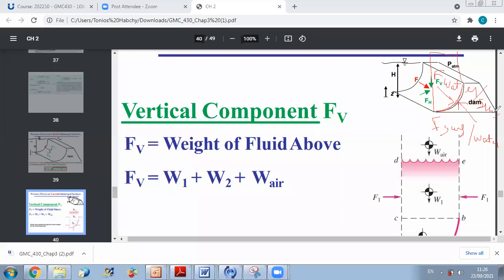So the idea here is, if I can find the force of the surface on water, I deduce by the principle of action-reaction the force of water on the surface. This is why we will take as control volume the water above the curved surface, and we will draw its free body diagram.